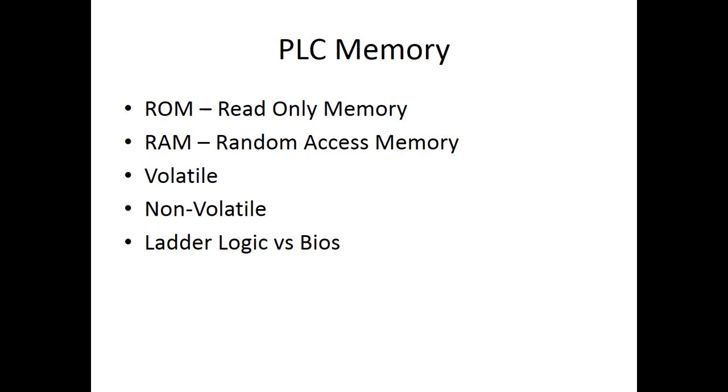PLC memory, there is the read-only memory, and so the read-only memory is the functionality of the PLC that is in the BIOS, and that's baked into the operation of the PLC. We can't really change it. The RAM usually represents your program, your ladder logic. Now there's a battery backup on the PLCs, so that if it goes down, your computer goes down, you don't lose the program. You don't have to have the computer hooked up to it. So basically, when you dump your program into the CPU, the battery backup keeps it, and it'll run without your computer hooked up to it.